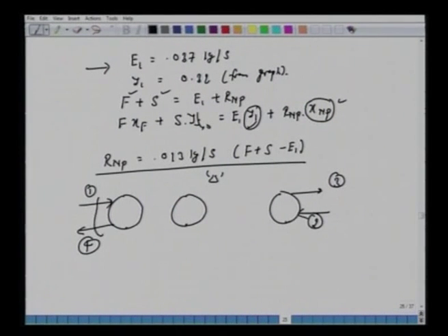And then we know the difference between the two, that we know delta molar flow rates, and this will also have a composition which we call x delta. These 2 points have also been located on our phase diagram. Then we can determine how many stages are required.